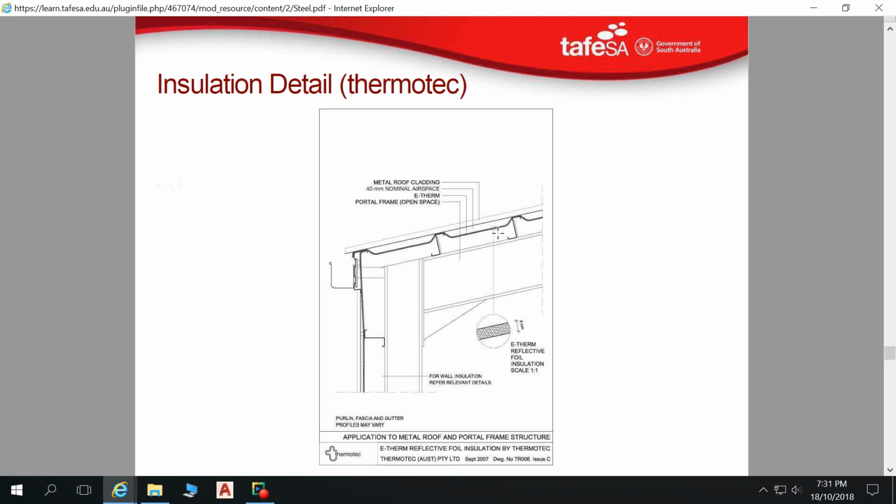But it also helps provide a secondary skin for any moisture that gets in. That moisture is stopped from making its way into the building, and it's directed out. So you lap that insulation out into your gutter, and then your other insulation laps in underneath that.